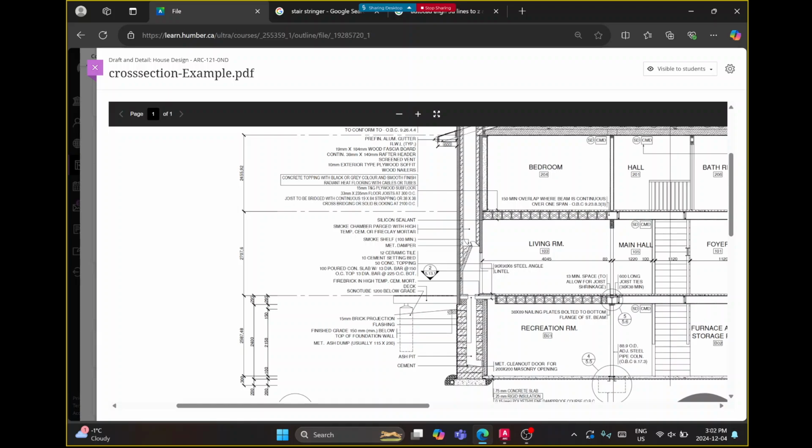And they put water pipes running through it, and that creates what's called the radiant floor. We pump hot water through those pipes, and it heats up the entire concrete floor, and so you get a nice even heat throughout the space. It's unusual that you would do it that thin, and unusual that you pair it with wood frame construction. Usually you just build a concrete floor and no wood frame construction, or you don't do this type of heating. So it's an unusual system they're using.